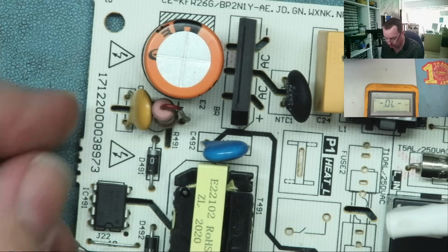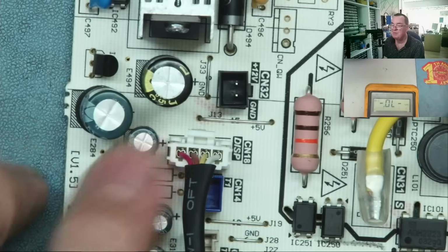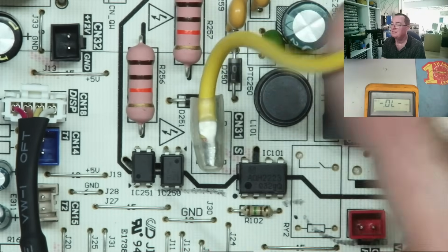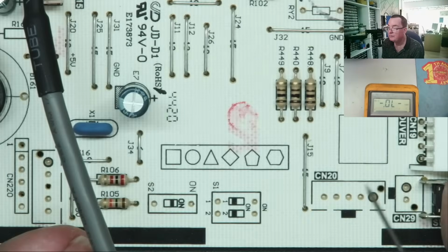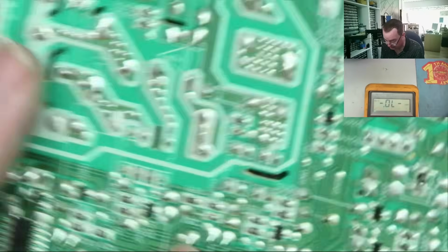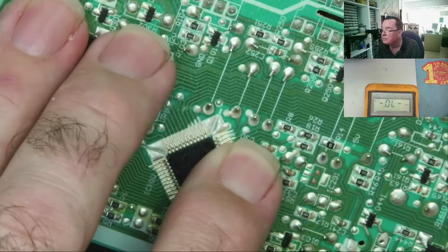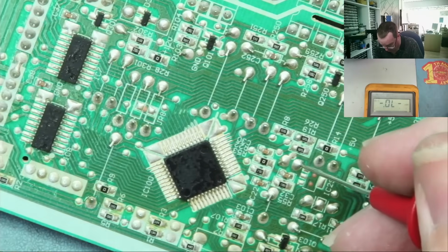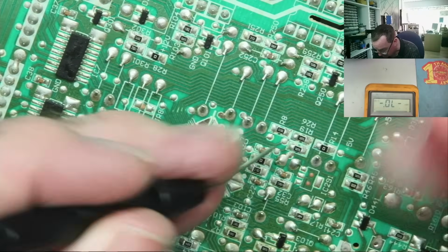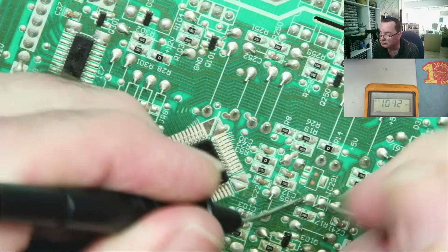Capacitors. Well, you can't really test these capacitors in circuits, but A, do we expect them to be faulty? Well, they look okay. Yeah, they look nice and flat. They probably are okay. What you can do though is to see if there's any shorts across any of the capacitors, because we can pretty much assume that a capacitor, no matter what it's doing, should not really short across it. So if we see any shorts on any of the capacitors, that means we've got a short circuit. Not a short circuit capacitor, but a short circuit on that voltage rail.